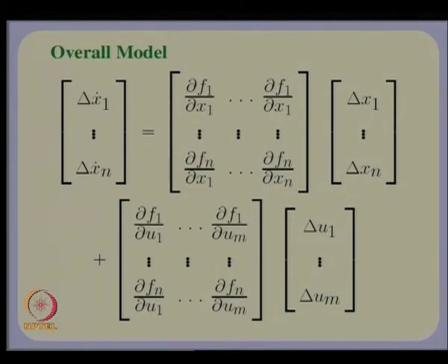In fact, I have taken out the partial derivative of the expression of Te with respect to psi d, psi q, Id and Iq and plugged in the equilibrium values. So, this is but a more general way of putting it. That is, you take out the partial derivatives or evaluate this Jacobian at the equilibrium values of the states.